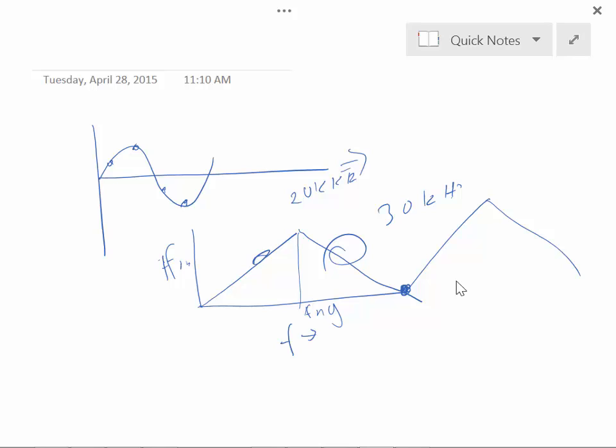So even though you can't hear it before you record it, once you've recorded this signal that's sitting there at 30 kilohertz, now all of a sudden it's within the range of the human ear. It's folded back. As a result, we have to make sure that we low pass filter right there.